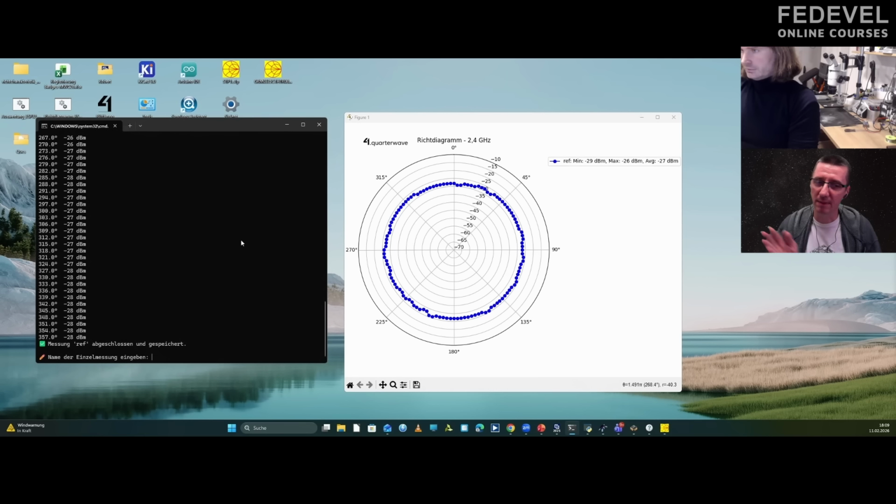But with this measurement, you are getting only some kind of relative numbers, so you don't really know how strong. Relative is okay. If I know the gain of my reference antenna, the relative is enough, because in development you need only indications: whether the antenna is bad or not bad, and in which way I need to optimize my antenna.